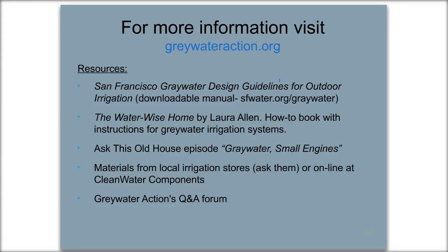Yes, you definitely don't want to overwater plants, particularly if you're in heavy soils where the water doesn't drain through very quickly. So you do want to think about your soils and if you have problems with pooling and slow infiltration of water. If you have sandy soils or quickly draining soils, it's kind of a non-issue. So let's imagine you have clay soils and they can become oversaturated. Then you can just turn off the graywater system. Usually the amount of graywater compared to a rainstorm is pretty minuscule, but you don't want to contribute to a problem if that problem is happening. So I would kind of play it by ear and see how the plants are doing, how your soil is draining. If you ever notice problems and the water is not soaking into the ground, you definitely want to shut off your system.